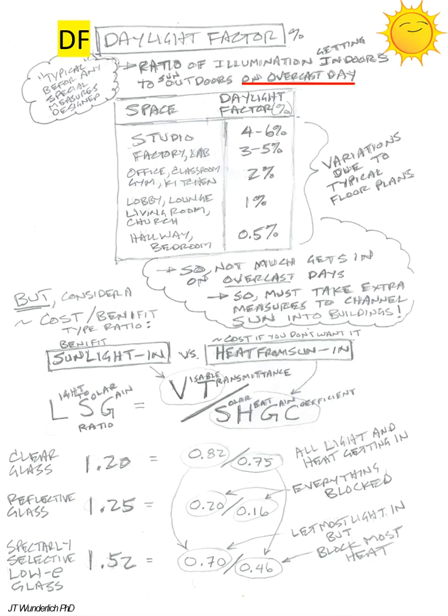And then you also want to consider, very importantly, there's a lot of balanced trade-offs of cost and benefits of this light to solar gain ratio. So now you're considering the heat from the sun that you're getting. And that's a cost if you don't want it. You may be wanting to heat up the house. It depends what time of year. So it's something you want to consider. And again, this is going to vary by location as well as time of the year, what you actually want as a goal. So you think about this a little bit. It's not just a this or that yes or no kind of thing.